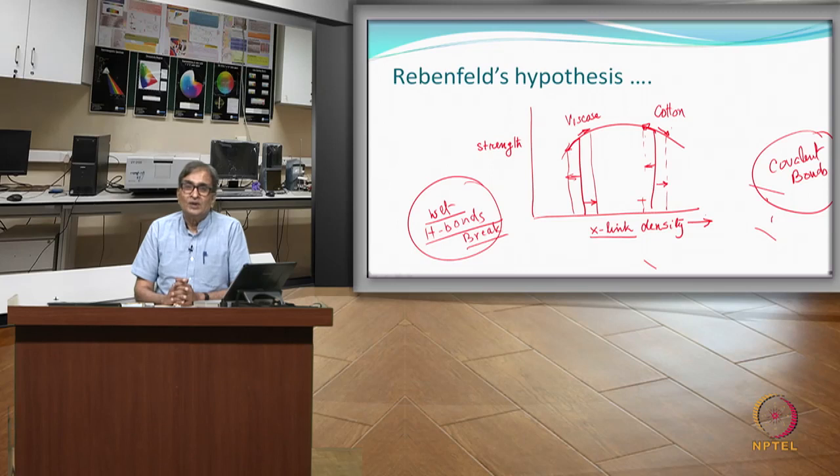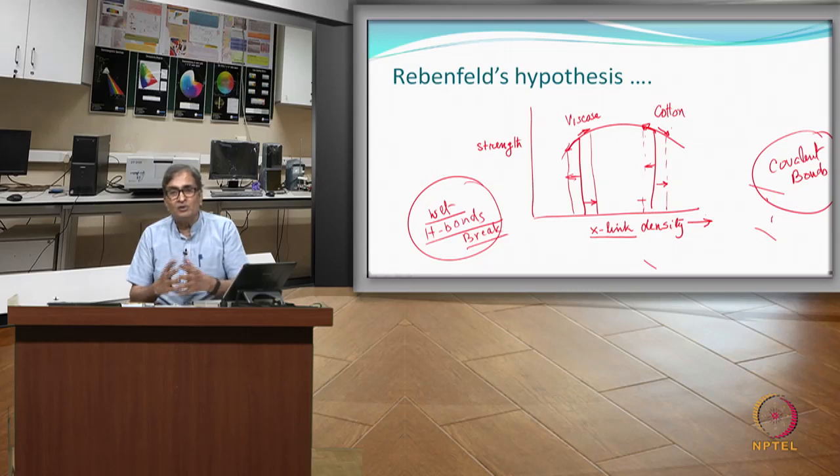The important thing is that in an absolutely amorphous system, if you put in cross-links, first, diffusion can take place better, and second, a uniform distribution of the cross-links will be there. And when you actually put load, the load distribution among the molecules is going to be uniform. All the molecules will share approximately similar amounts of load, and if everyone is together, the total strength is more.